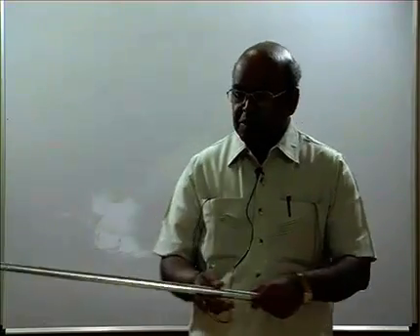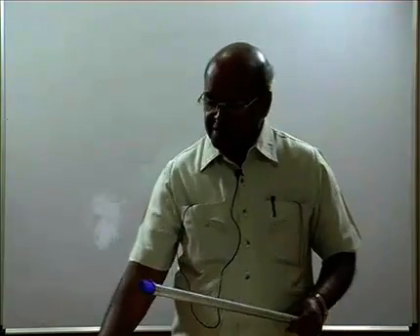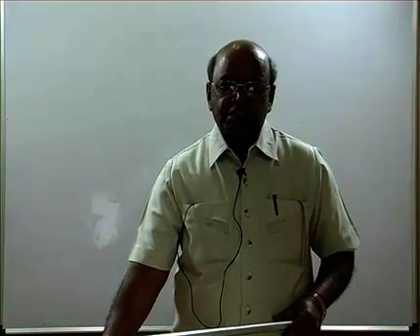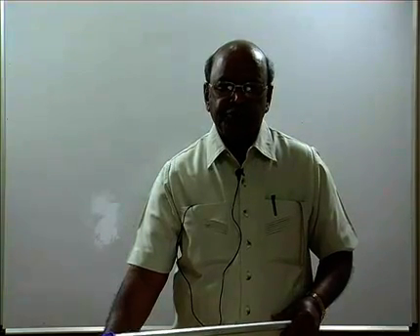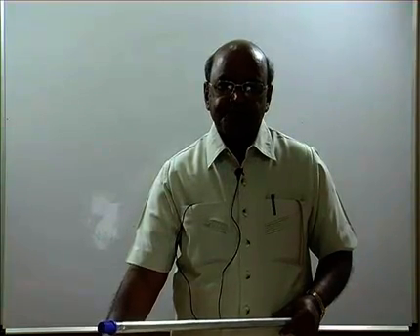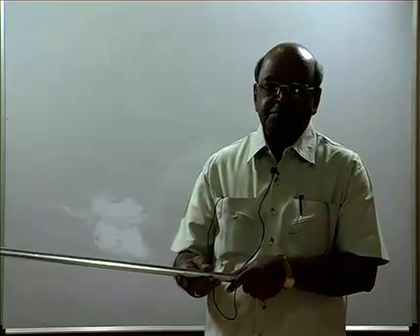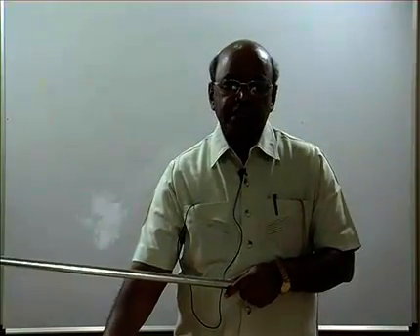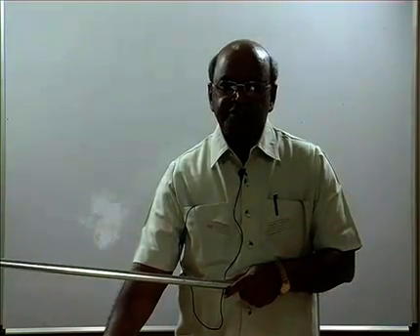Next, what you do is take only one angle theta. So you rotate the front view as shown at B, and correspondingly you get the top view. So I am calling it the second case as AB2. First one AB1, second AB2. Now third, I am taking only phi angle. So it is parallel to HP, inclined to VP. So here I am taking it as AB3. So top view is having true length, front view is reducing.